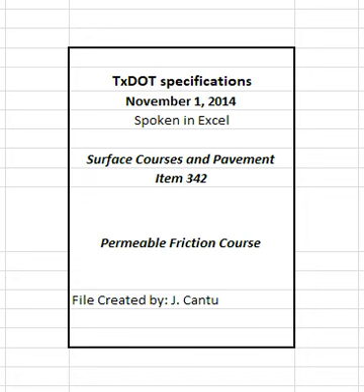4.4.2.1 Contractor's Responsibilities. 4.4.2.1.1 Gyratory Compactor. Furnish an SGC calibrated in accordance with TEX 241F for molding production samples. Locate the SGC at the engineer's field laboratory and make the SGC available to the engineer for use in molding production samples.